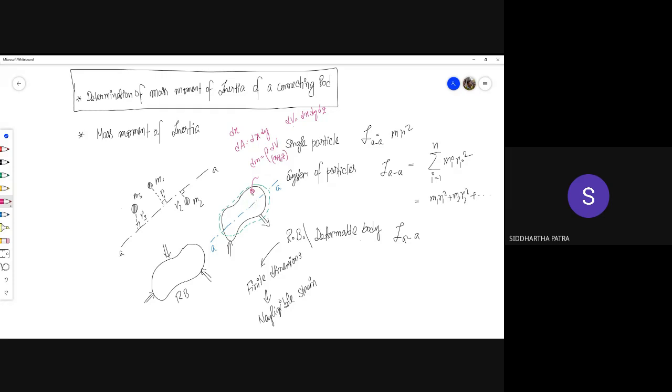So you take a differential mass, and you also need to take the normal distance. Imagine it's a 3D object. Try to have an understanding of the third direction, which is normal to the plane. So this line on a projection might not look like a perpendicular, but it actually is. And the length of that normal is r on the axis.